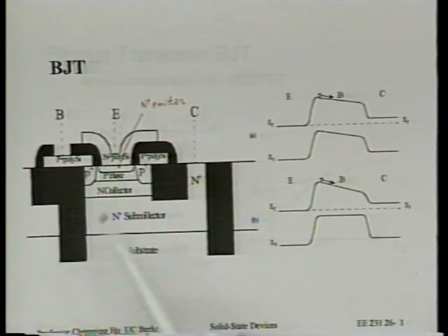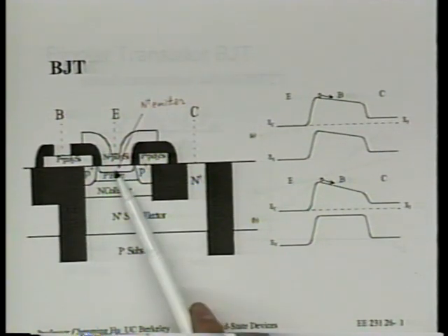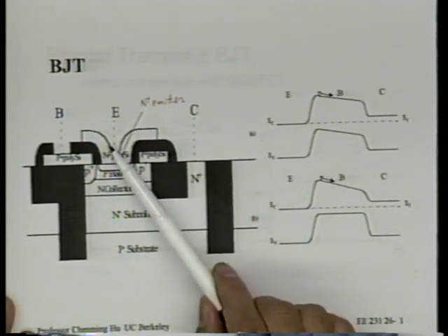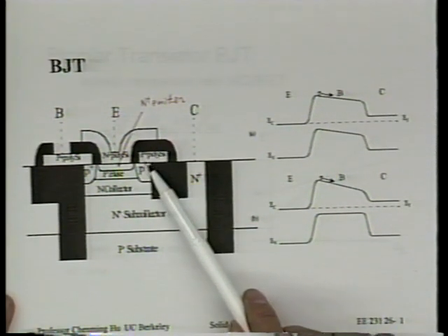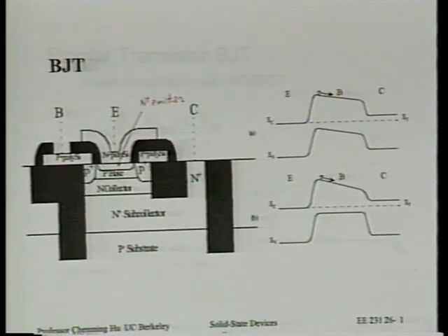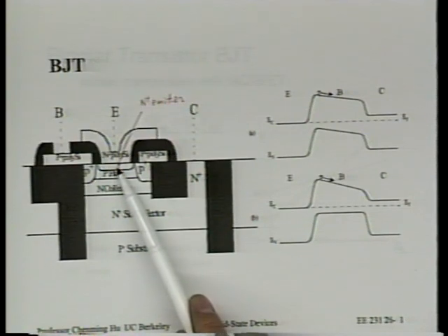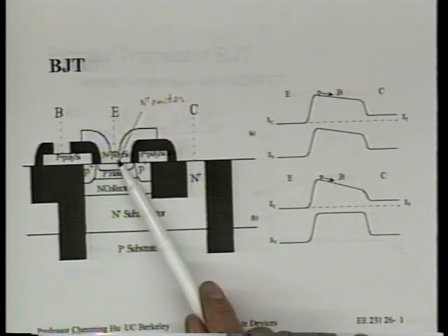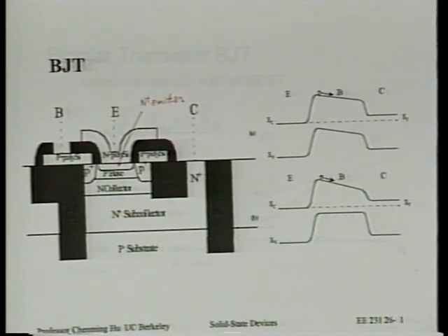All right? And the emitter contact is made through this N plus poly. So right on top, the N plus poly can sit on top of the P plus silicon contact, separated by an oxide. Okay? And in fact, this N plus poly is where the diffusion dopant comes from. And this poly is often called part of the emitter. We call it a polysilicon emitter. All right? And so that's how a transistor is made very small.